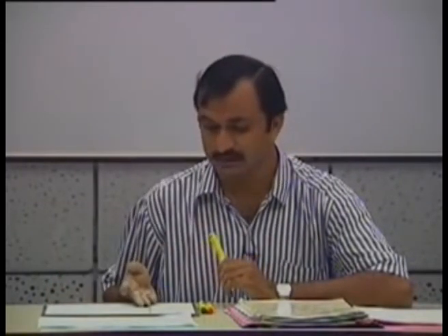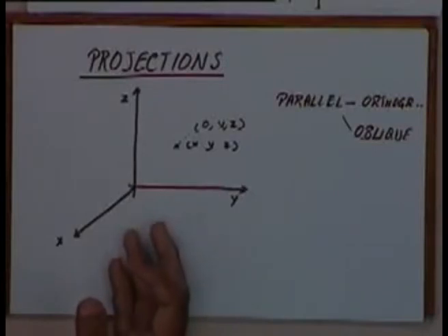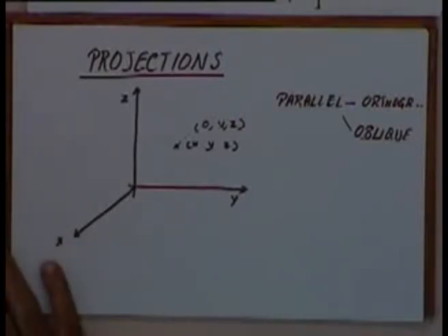The one you have there is oblique. What I have here is oblique. Like when the observer is normal to the coming rays, and if it is at an angle. Okay, I'll give you the definition. In an orthographic projection, your projecting rays are perpendicular to the projecting plane.